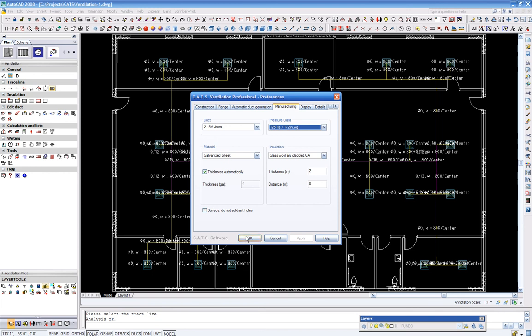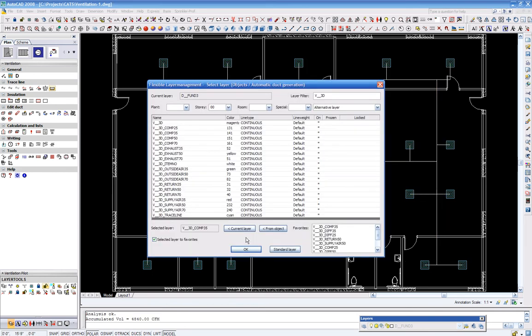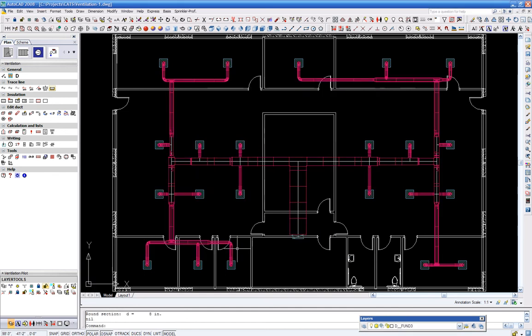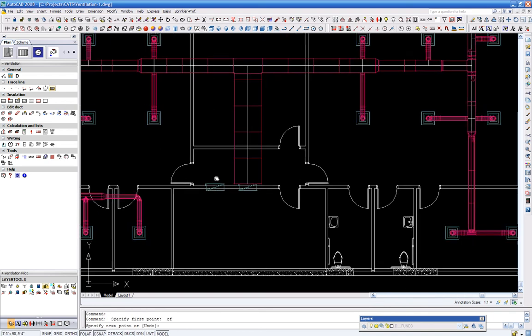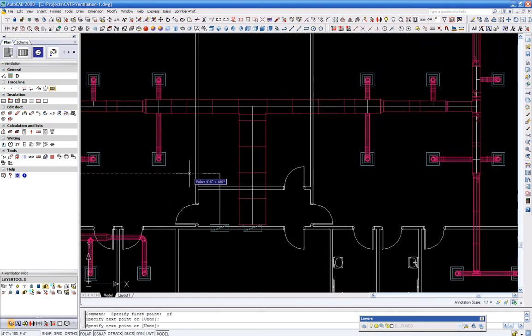We will select the layer for supply duct. The software will now create the three-dimensional drawing. The duct size, width is now created, and we have previously selected our duct height. We will now copy the fire damper. Relocate 5 feet to the left to create our return air duct penetration. We will now draw our duct center line for the return similar to as we did for the supply duct.